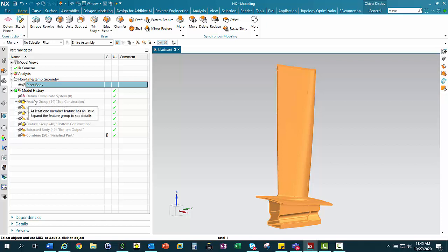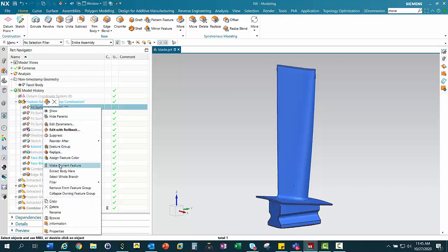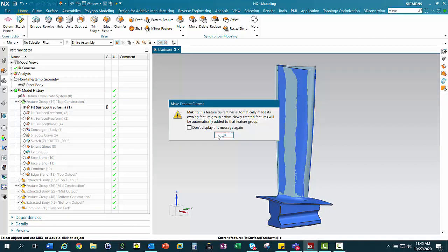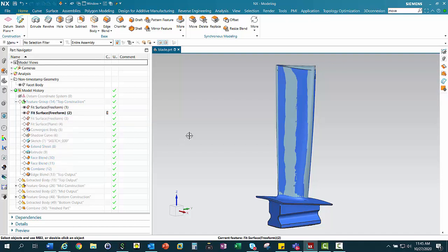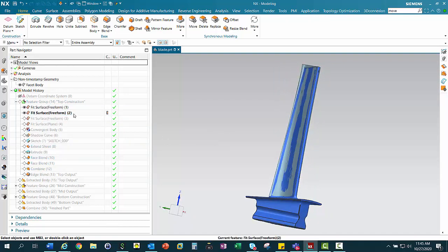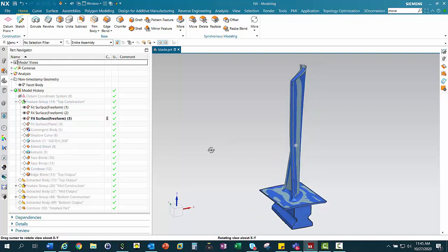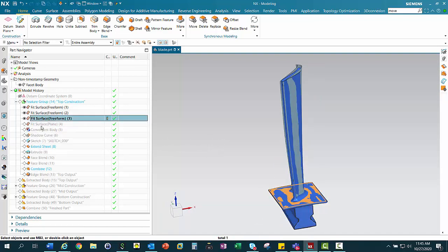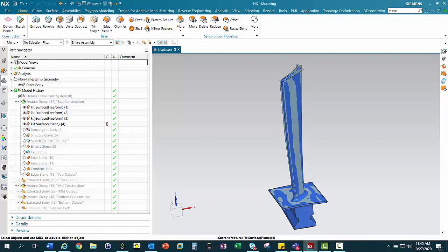And the task was to reverse engineer this into a BREP solid. So if I go through the steps, we'll go into the first step. And the first thing we would do is start extracting data. So we would extract these faces one at a time. And continue extracting. Now the goal here is to do the top side. So we want to get the top, and then we'll do the middle, and then we'll do the bottom, then we'll combine them into one solid.